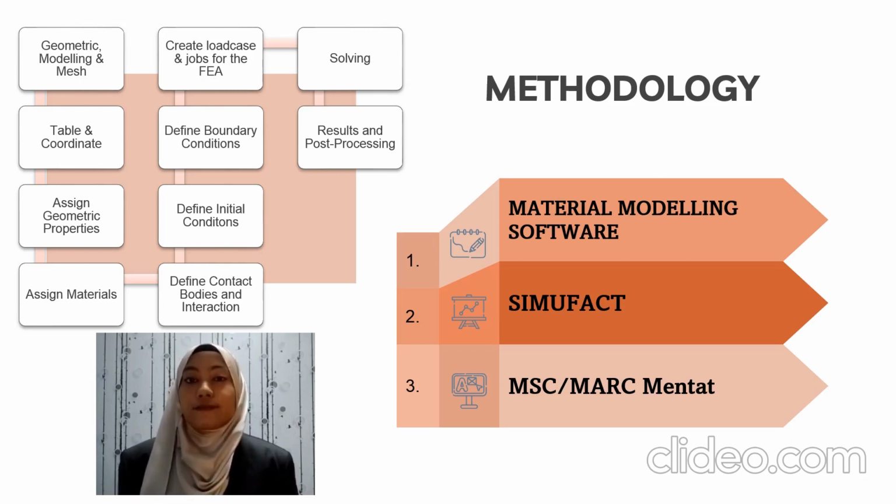Simufact Welding functions as a tool for structural welding modeling, calculating distortions and residual stresses based on a mathematical description of related heat sources in their most basic form. The data from Simufact later can be used in MSC Marc Mentat for modeling.